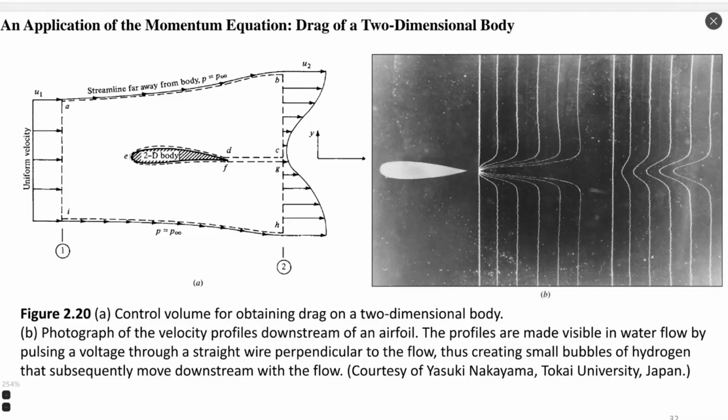Which is the problem we might see here? We have, for example, some airfoil with known geometry, and we would like to use our flow equations, in particular the momentum equation, to obtain the drag over this body. What we can do, we can measure this drag. Not always, right? Sometimes we can, but the momentum equation has such a nice property that applying this equation to an experiment, you do not need to put any additional tool or sensor to measure the distribution, or the value of the drag of the airfoil.